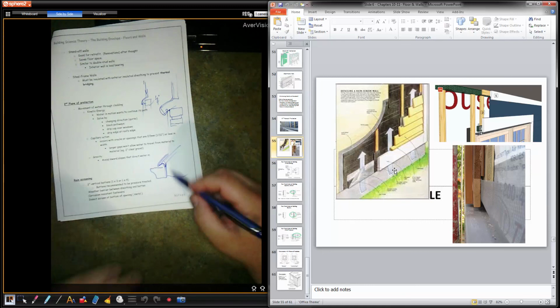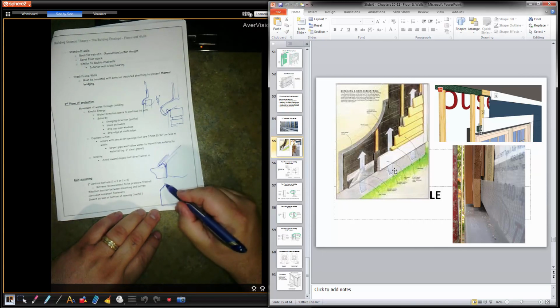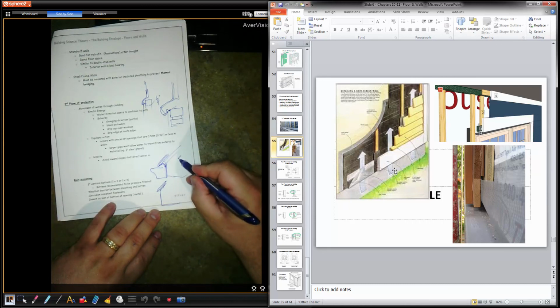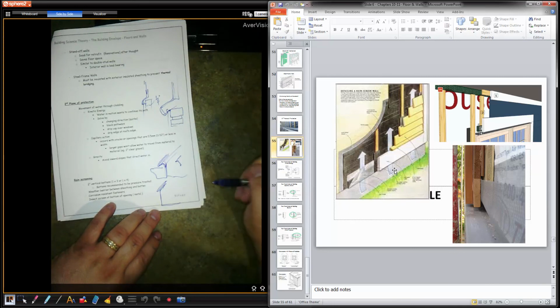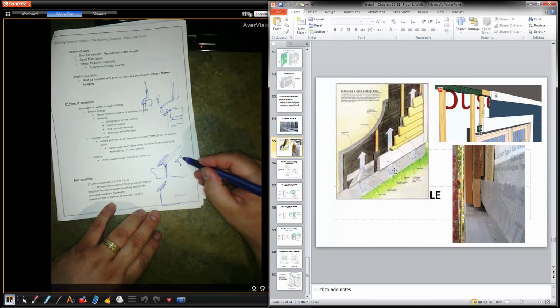So a lot of older roofs just have fascia going underneath the shingles, coming down, and then underneath the building. They don't have the drip cap. Then they have shingles like that. They don't have the drip cap. Drip cap is a piece of metal that we install on the building. Looks similar to that. Okay, so that's about 2 inches, maybe 1/2 inch, maybe 1 inch, and then like a 1/4 by 1/4. That gets installed, and then the drip edge is nailed onto the building, and then fascia goes up in that crack. There's our rough fascia, 2x6 or 2x4.